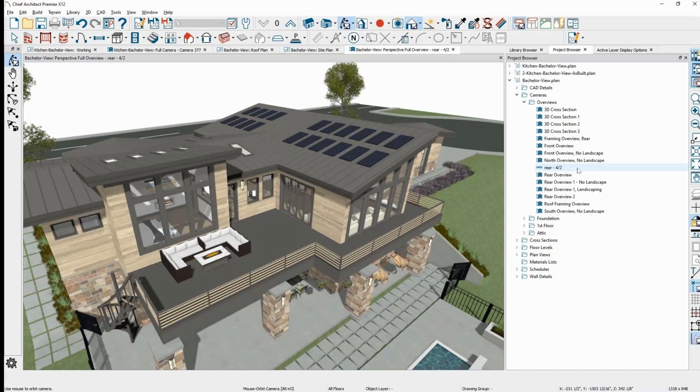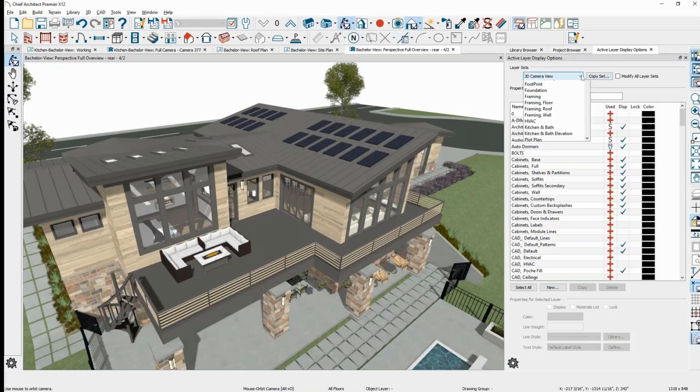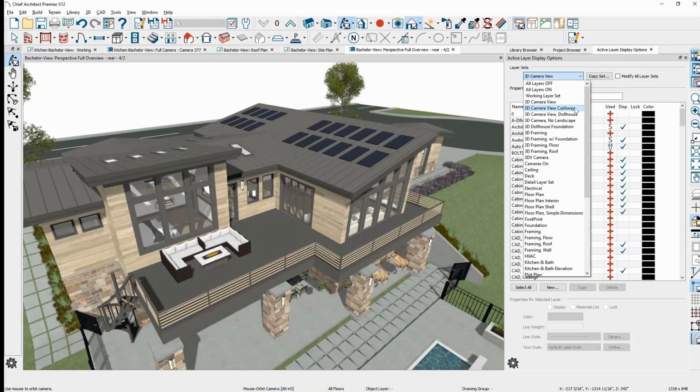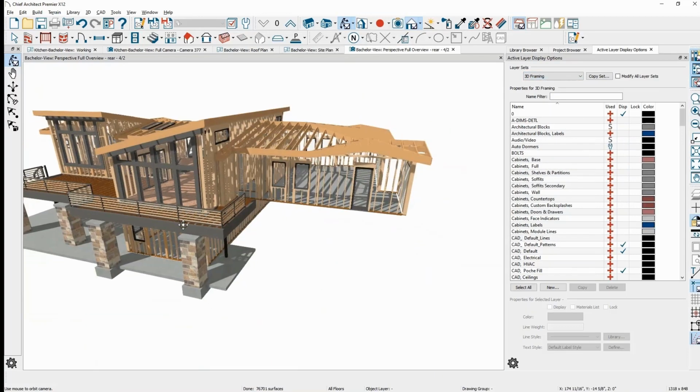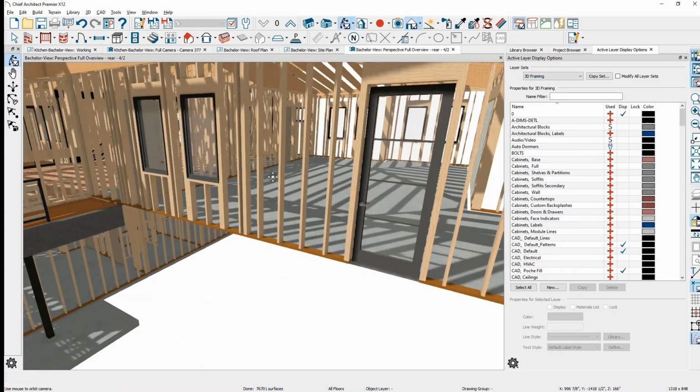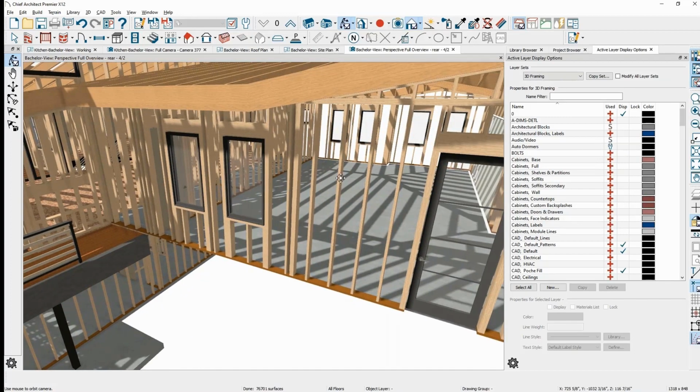Great. Your second question, you asked about framing. Let's switch our view here to framing. Let me just switch my 3D view to framing, 3D framing. So when you're talking about blocking, if we pick on this wall right here and you needed to do blocking in here, you want to run 2 sets of blocking, or you want to set the distance between your blocking?